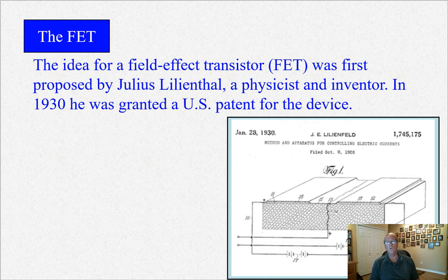FETs are most often used for switching applications. In other words, on or off. In fact, all integrated circuits are made with FETs, field effect transistors, a bunch of them. I mean, there could be a billion field effect transistors in a common microprocessor these days, or FPGA. So that's primarily what they're used for. There are linear applications, however, for field effect transistors, and we'll look at some ways of doing that.